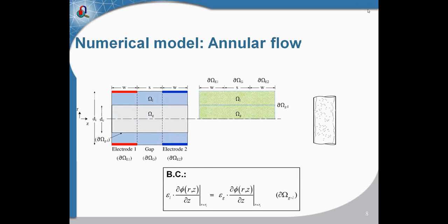On this slide, you can see again a schematic drawing of the ring type sensor, here basically for the gas core model. Here the 2 phases are separated into 2 blocks. That means the inner one representing the gas core with the relative permittivity for the gas phase, and the outer one representing the liquid film with the relative permittivity for the liquid phase.